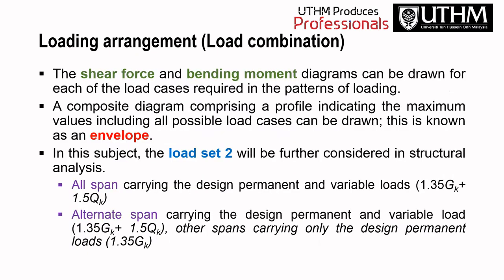Okay, so the shear force and bending moment diagram can be drawn for each of the load cases required in the patterns of loading. You need to draw this. A composite diagram comprising a profile indicating the maximum value, including all possible load cases, can be drawn. You need to draw it and combine all the shear force and bending moment diagrams in one diagram, and it is called an envelope. So in this subject, load set 2 will be further considered in the structural design. So we will use load set number 2.